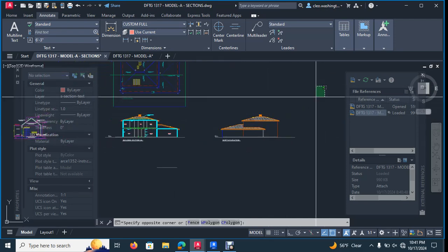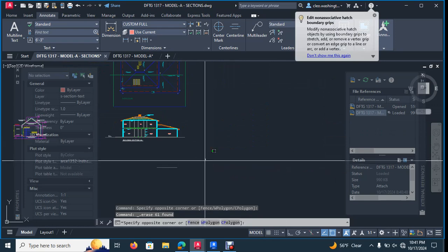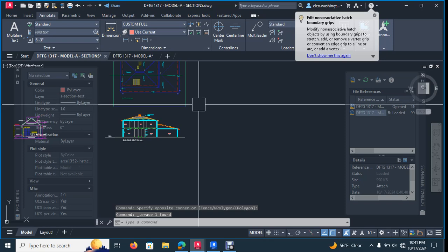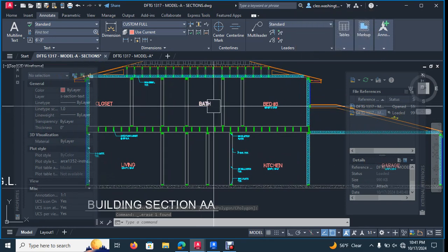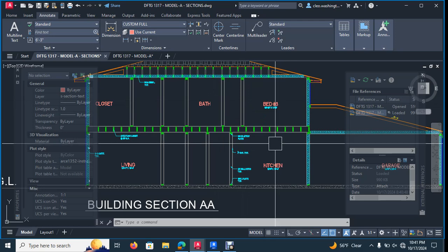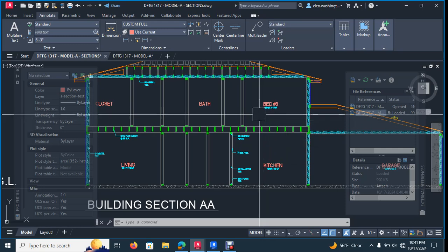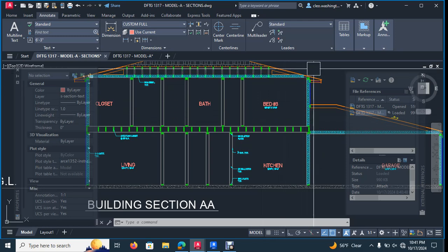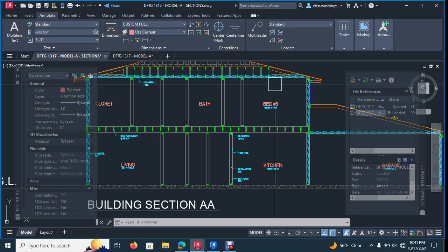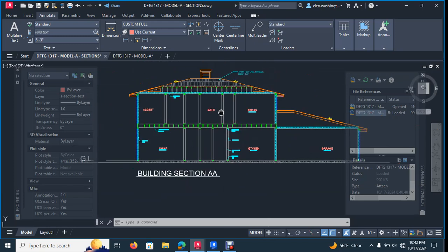We won't do another one with this one, so we can delete this one. But those other two elevations, one of those we'll modify to actually get the building section. Then after we get the building sections drawn, we'll have a session where we go back and update the floor plan. We will also update the elevations to reflect what's drawn in the building section, because the building section is the motivating factor. It's going to drive all the other drawings, because a lot of times when you start putting the components together, things may get a little bit wider or a little bit tighter. So you have to go back and update the drawings so they can be consistent all the way through. Okay, so good stuff, guys.